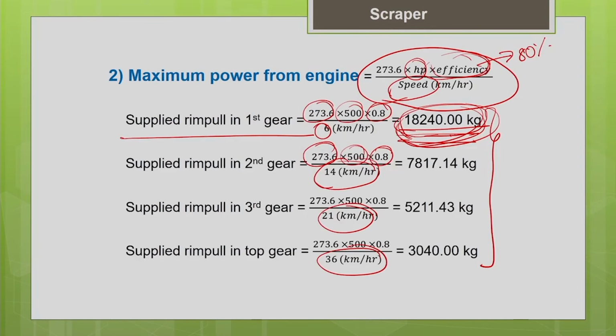Now, the horsepower rating is determined at standard conditions, standard temperature and pressure, as we discussed earlier. Variation in temperature and pressure will affect the efficiency of your machine, because all the horsepower rating done by the standard organization is at standard conditions of temperature and pressure. In this problem it is given that the machine is working at a higher altitude, say 600 meter.